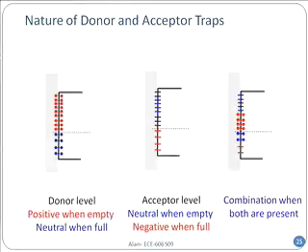I have plotted the conduction and valence bands, just close to the interface between silicon dioxide and silicon. Now, the blue and the red are actually the same surface states. The dotted line is the Fermi level. Let's assume that these levels are donor-like. These are not donors, these are donor-like.